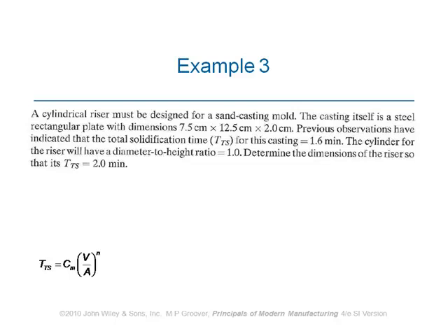A shape where we have got a higher V over A ratio. And which geometry has got that one compared to other ones? Which geometry has got a higher V over A ratio? Spherical shape first, followed by cylindrical shape. And that's one of the reasons that risers are always made in cylindrical shapes, because we want to lower the area as much as possible and raise the V over A ratio. Okay, making a spherical shape is more difficult, so often we make use of cylindrical shape. But spherical shape is still fine.